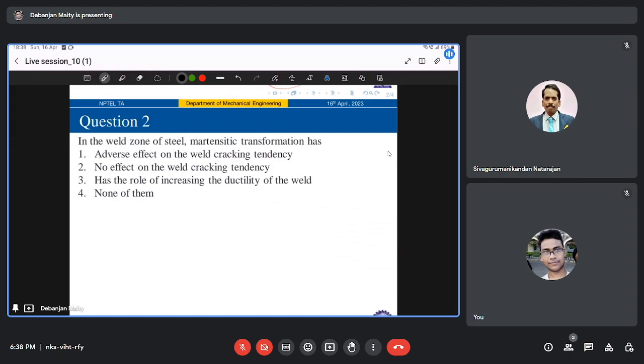Now, how is this loss of ductility happening? If you see, many eutectics are inherently hard and brittle, and thus this lowers the ductility of a material, right? The reason for this is twofold. First, in a binary system, eutectics always consist of an intimate mechanical mixture of two phases, right?